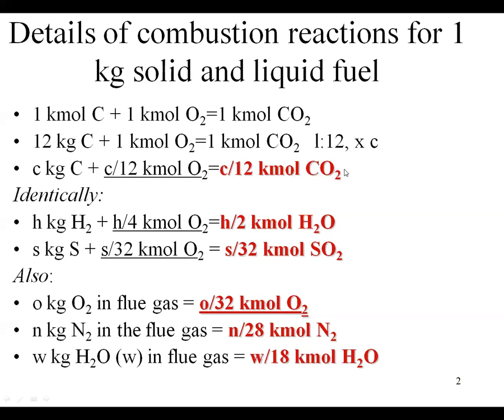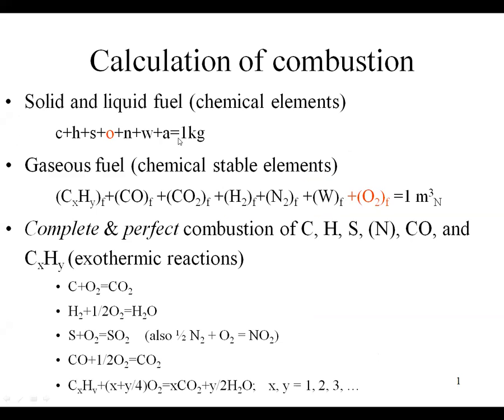If you understood this interpretation that I gave you, identically you can deal with all the reactions of hydrogen, of sulfur, and so on. And finally, we have to decide how much oxygen I need in order to have a perfect combustion for all the elements that are burning here.